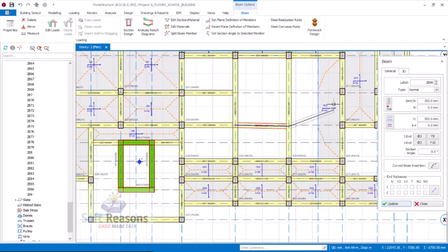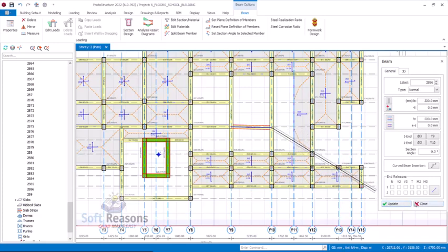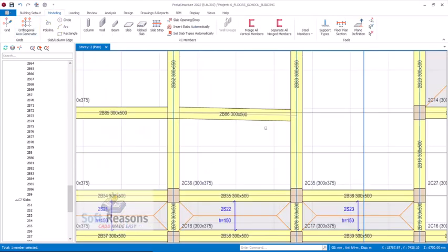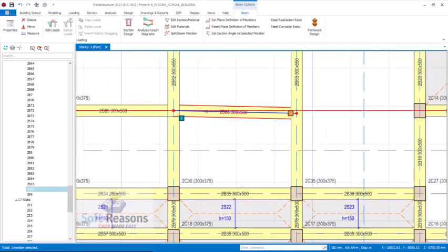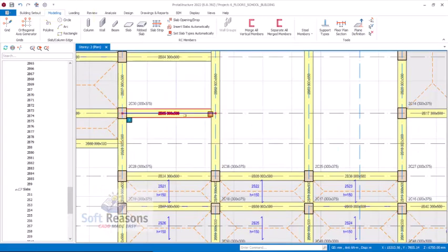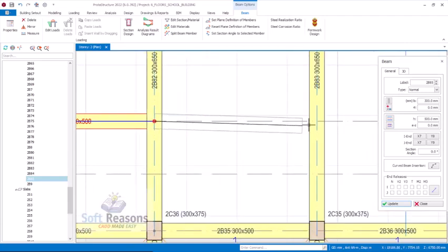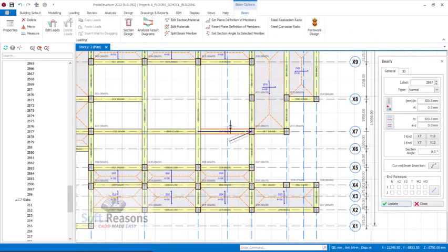At this point, we wouldn't have this cantilever, although we generated everything, so we get rid of the cantilever first. At this floor we don't have such. Always pay attention to be sure that you connect your beam at both ends to the grid line intersections. Delete that, save this project first. Select this, right click, click on properties, pick this point all the way here, just like this.